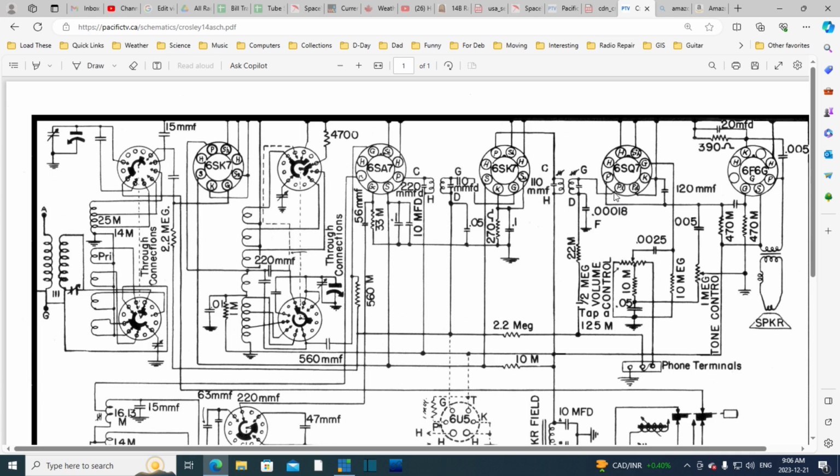But once the rectification has taken place, and it's occurring in this tube, that rectified signal is what's, I hate to use the word, but I will, tickling the cathode in the other part of the tube, the same cathode, and causing an effect, which is what is causing the signal to make it through this tube, not even bothering with the volume control. A small amount, I don't want to say leaking, a small amount is being produced on the plate, which is getting over here, and we're hearing it.